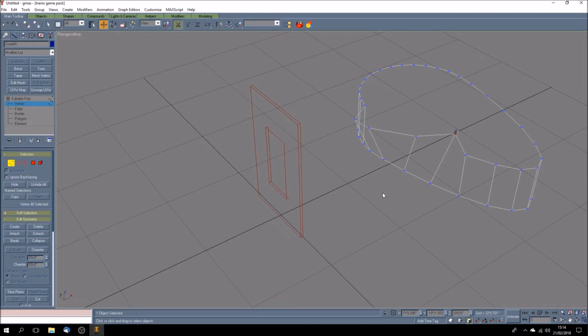So there we are, that's editable splines and extruding. They are combined with those basic primitives, standard primitives. They are most powerful ways of creating the little bits and pieces that go together to make your more complex model. I especially like using them to make walls with spaces for windows and dropping things in. There is an alternative way of doing it, which involves punching a hole through a standard primitive, but oh dear, it makes all sorts of problems. So I prefer this method.